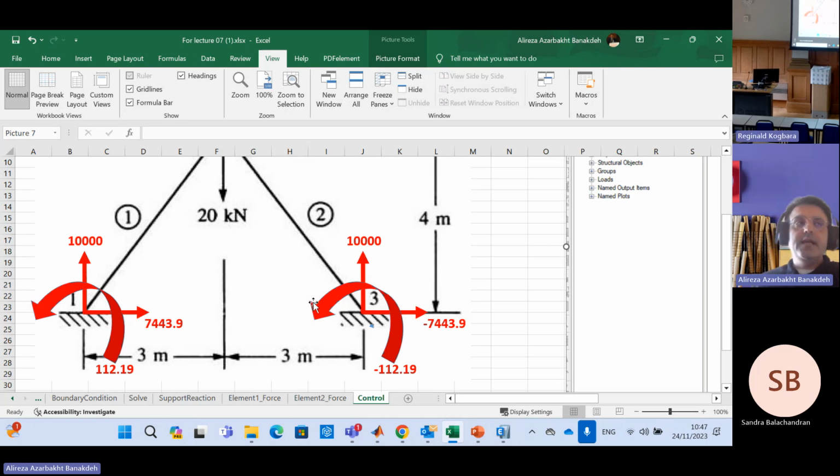So when you're working with external forces like 20 kilonewton, which means 20,000 newton, when you come up at the end of the day with the summation of Fx not equal to zero, but equal to 1 newton, for example, 1 newton compared to the 20,000 newton is practically zero. From an engineering point of view, it's zero. But if you come up with some sort of numbers like 500 compared to 20,000, it's not zero. You have certainly made some error in your calculation.